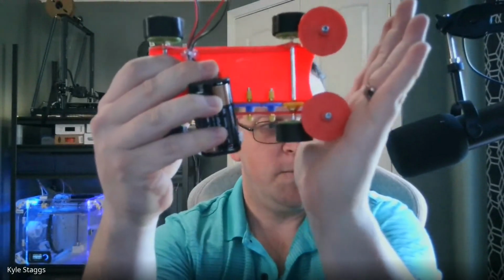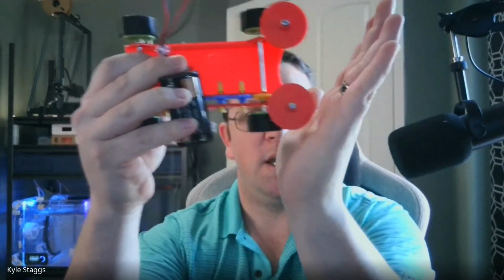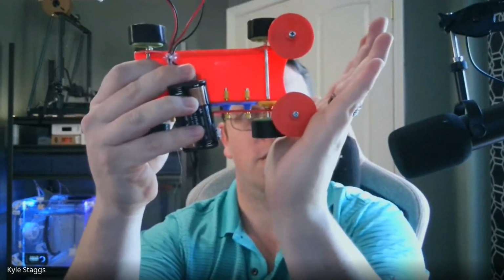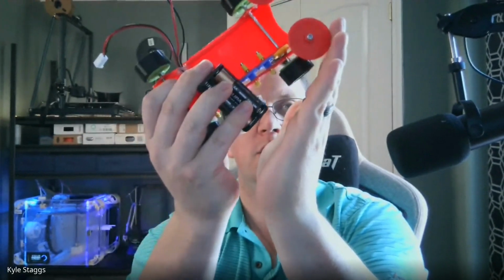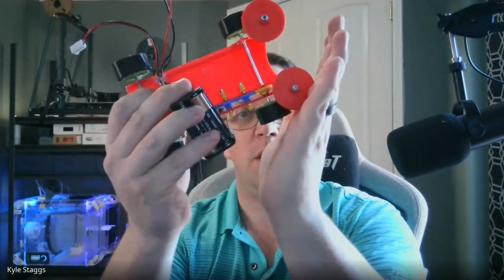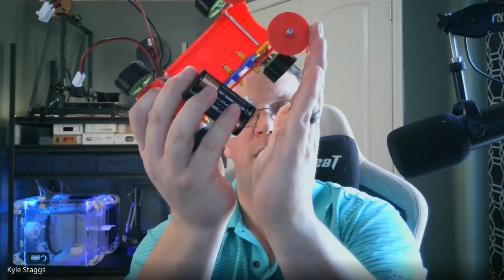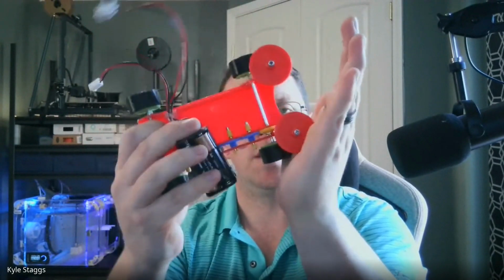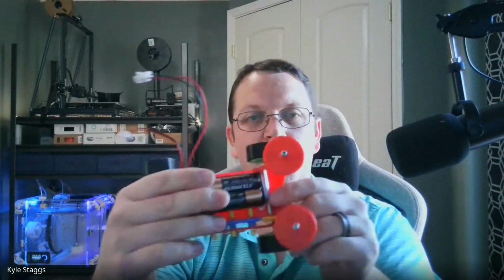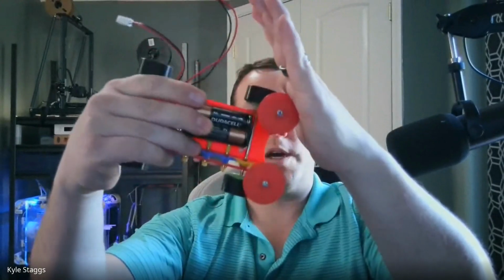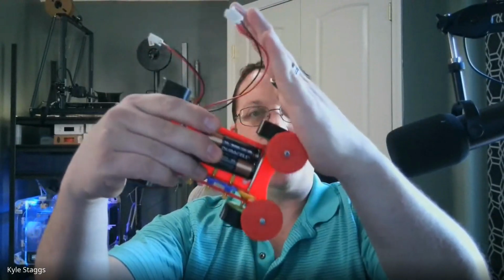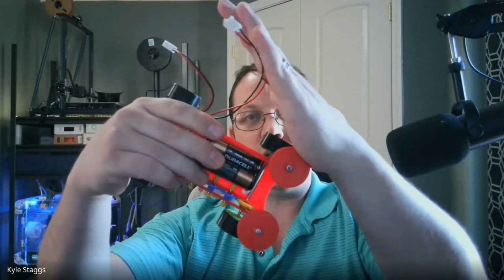What you don't want is the tires hitting. Use maybe a 60-degree angle as a reference point. You do not want the tire interacting as the car turns. You do not want that tire to be able to interact with the wall at all. At no point can the wall grab onto that tire, because if it does, you're going to lose tons and tons of speed fast. So you don't want to do that. You want to use something like this where that radius, no matter which direction it's going, the tire cannot touch the wall no matter how hard it tries. Even if it's flexing, it cannot touch the wall.